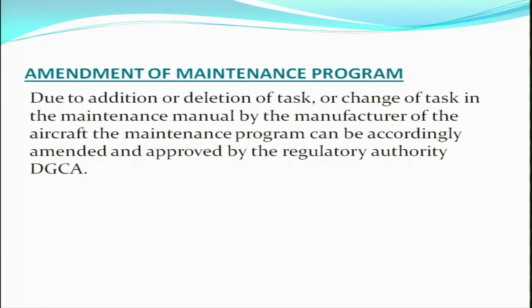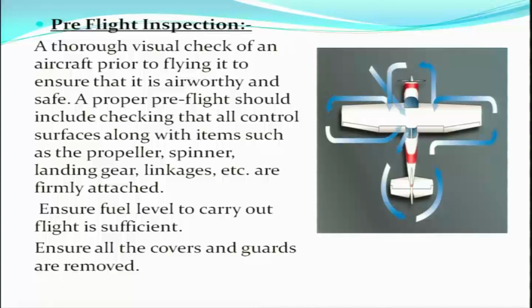So due to addition or deletion of task or change of task in the maintenance manuals by the manufacturer of the aircraft, the maintenance program can be accordingly amended and approved by the regulatory authority, that is DGCA. Now coming to the pre-flight inspection, we have just seen generally the pre-flight inspection is carried out by the pilot, but we will just see what is a pre-flight inspection.